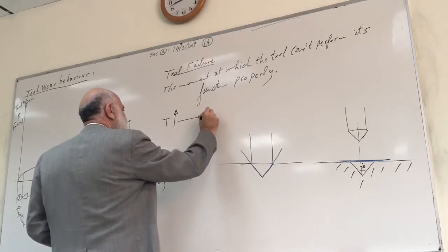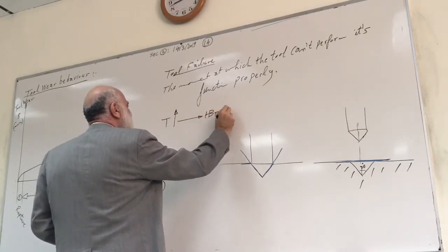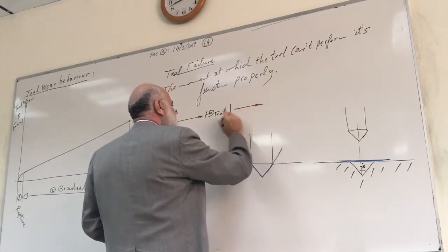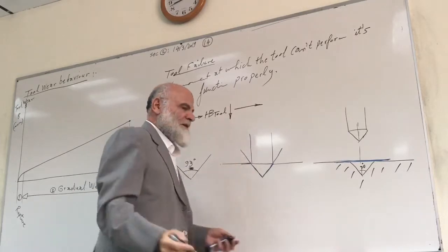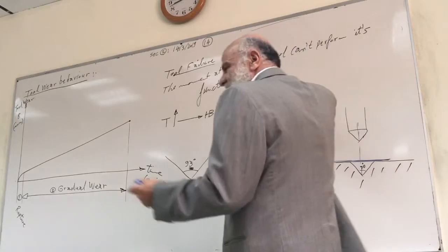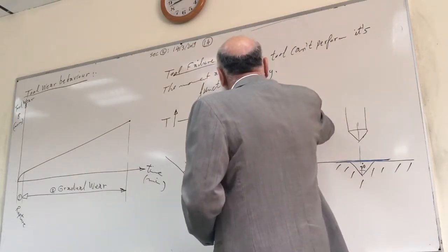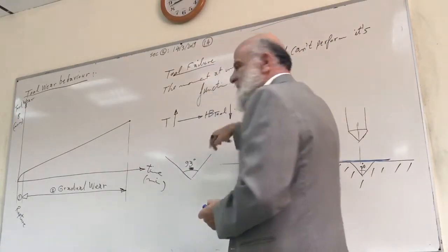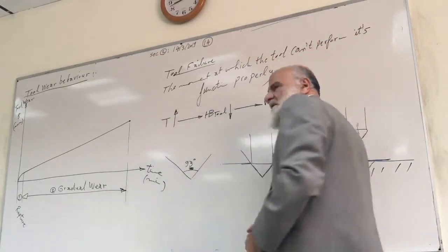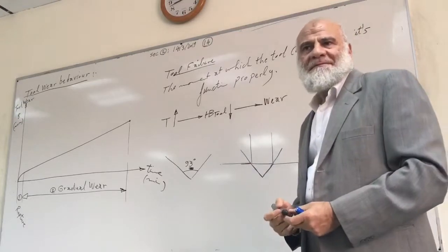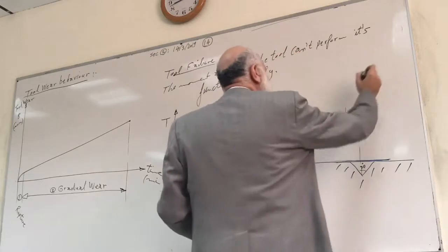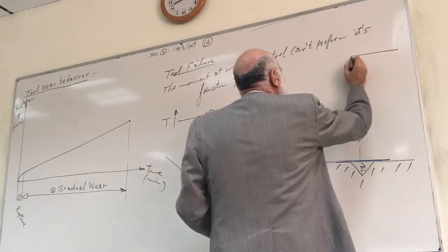The hardness of a tool, what will happen? Decrease. And when the hardness of the tool decreases, bad things happen to the tool. The weakest and simplest of them, the first, is wear. But if the temperature increases more and more, the tool becomes the workpiece. The tool will be workpiece, and the workpiece will be tool, to do what? To do what's called thermal failure.